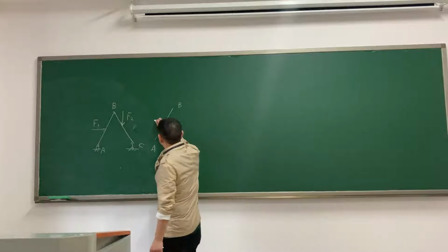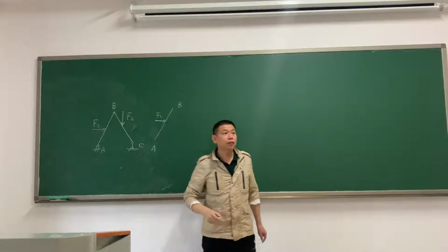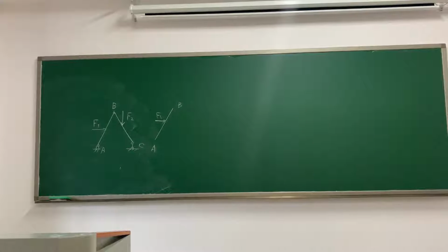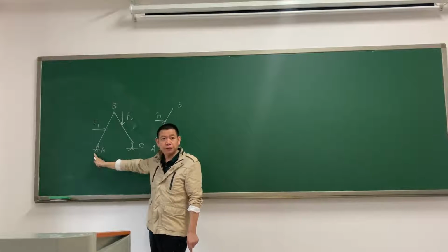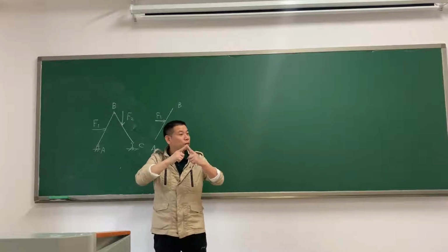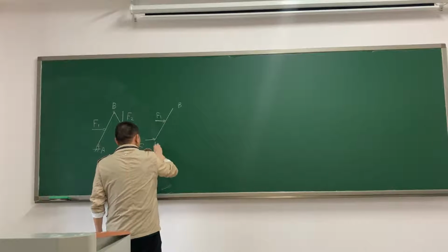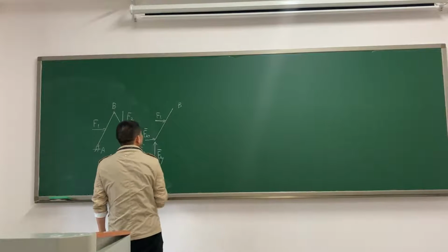Applied loads, we just copy it. F1 is the applied load. Reactions according to the kinds of support. What kind of support is it? A pin support. How do we draw the reaction? Two perpendicular forces, FAX and FAY.